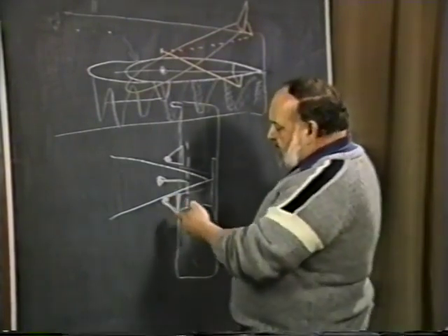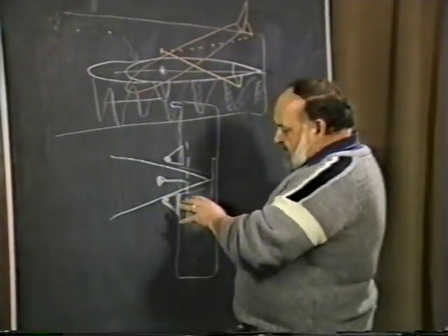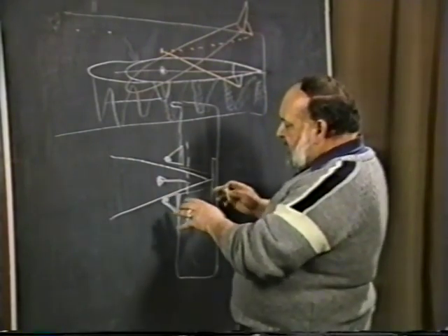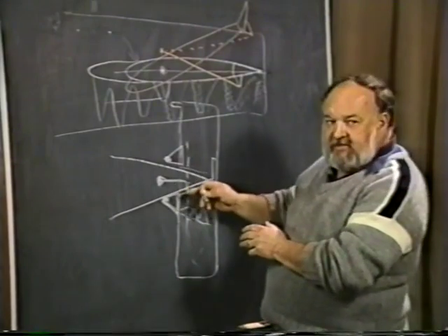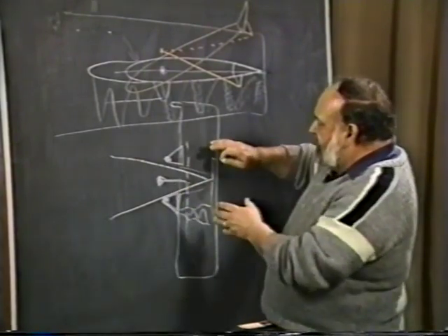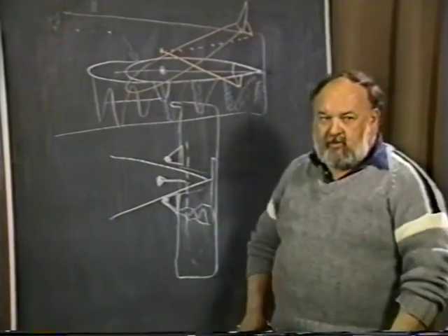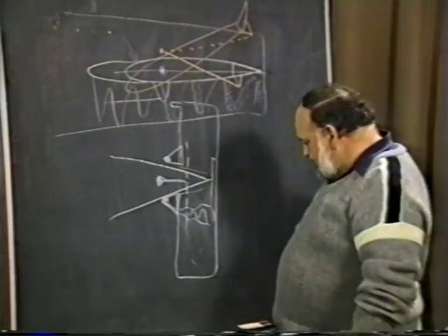You can make this go quite large if you want to, and make it close to the surface of the fuselage without any real problems whatsoever. Remember, however, to include this area when you're calculating the total area of this wing so you can determine your quarter chord to know where your hinge point should be.